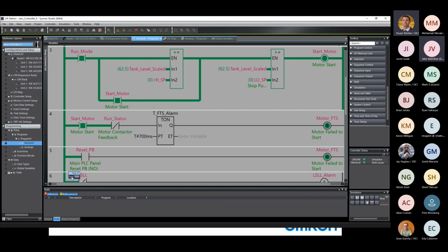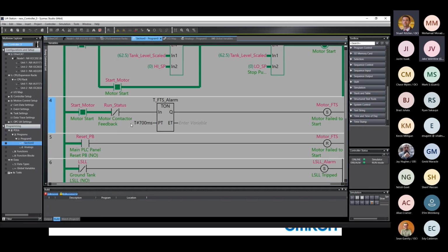So that pretty much confirmed it right there. The run status and the level switch, you're going to have to force quite often when you're doing your simulations just to avoid the alarms, which is true in commissioning quite regularly.